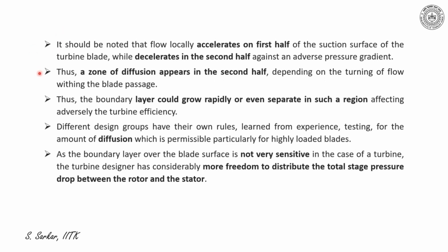Thus, a zone of diffusion appears in the second half, depending on the turning of flow within the blade passage. Furthermore, the boundary layer could grow rapidly or even separate in the zone of diffusion, affecting adversely the efficiency of a turbine stage.